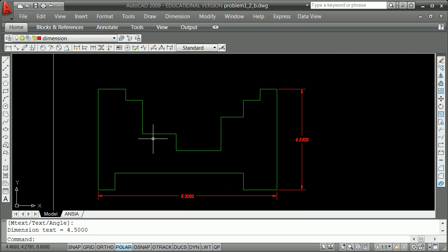Grab the object, pull it out, and hopefully you get to see that you've done things the same way. Later we will see you can add line types that have text in them or symbols, so it will show in what direction the lines went. This may seem small, to many it does, but understanding that lines on the page actually, or in the drafting plane or in the design plane, have direction is a habit that if you establish the thought early, you'll be much better off. So that was using polar snaps to do the same, once again without dynamic.